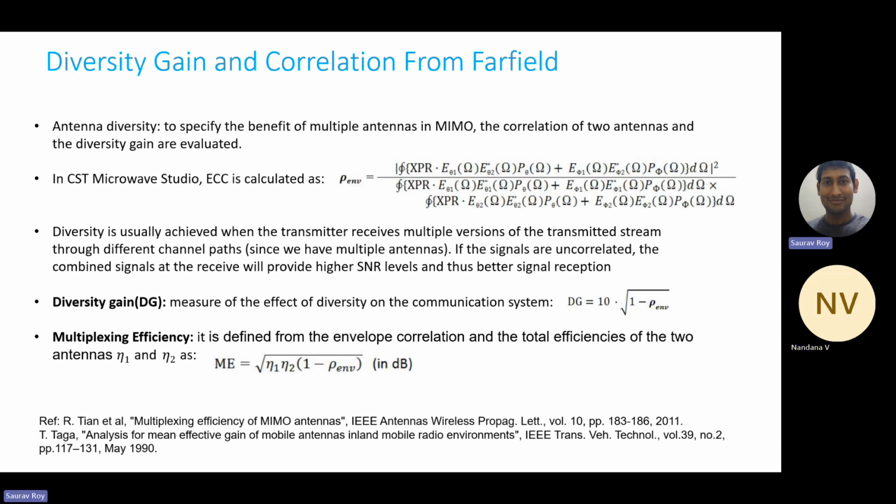Generally our anechoic chamber is designed for above 900 megahertz or something, it will work. So you can calculate easily. It should be more than the wavelength at 900. You can easily see that the length of these shapes and the distance between shapes is even more than this wavelength at 900 megahertz. That is how we can say this surface has irregularities more than the wavelength, so that it will not reflect.